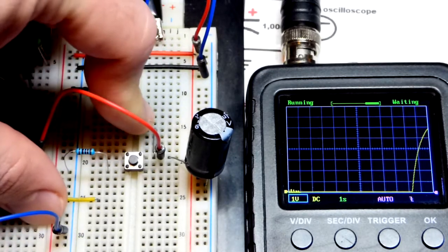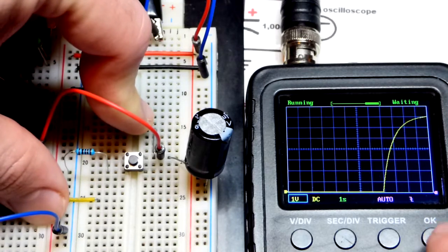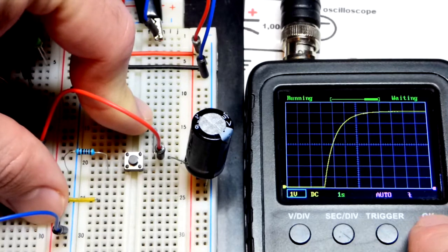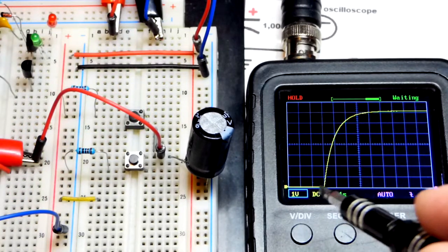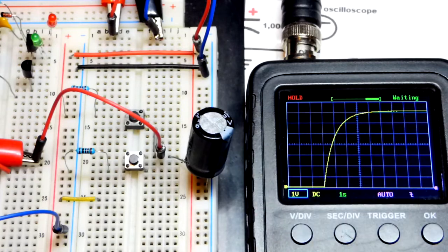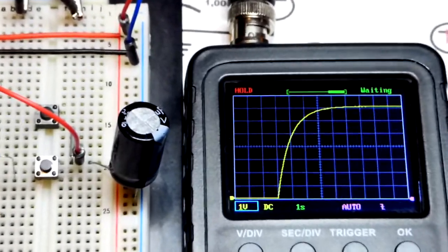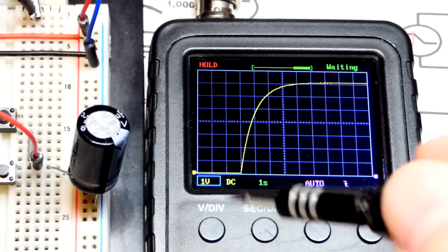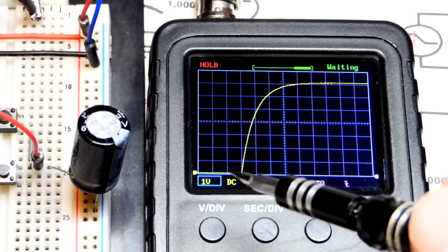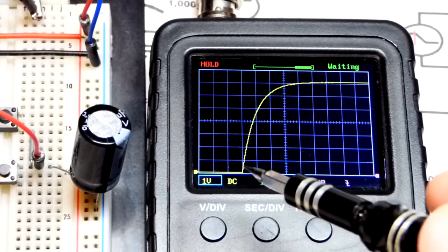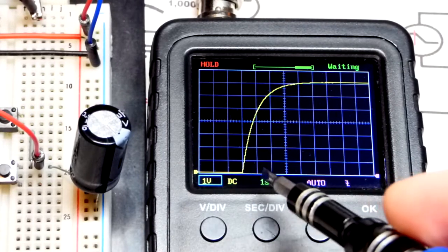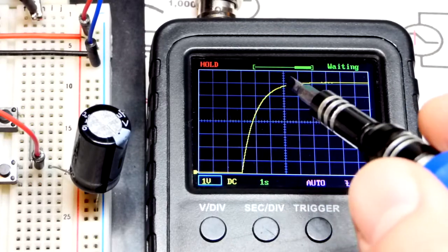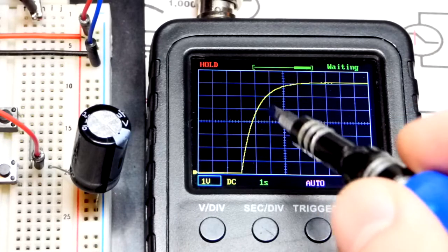And so I'm going to charge it up. I have the power supply set to 7 volts because we have 8 squares here, and so we can easily see up to 7. So I'll try to pause it right when we get there. Since it's a 1000 microfarad capacitor, 1/1000th of a farad, and we have a 1000 ohm resistor, 1000 times 1000th is 1 second. That's how long it takes to get about 2/3 of the charge. As you can see there, we're about 2/3 of the way. And then the next second's another 2/3, and so on.